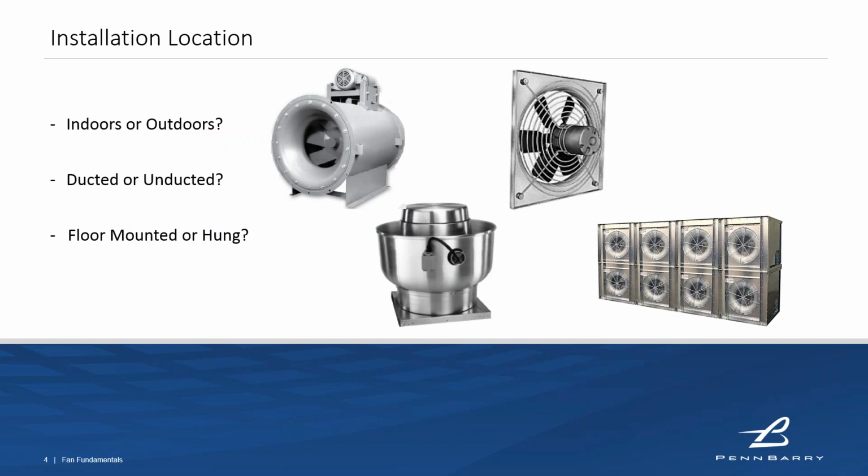So then, going into installation locations: are you going to put this fan inside? Are you going to put it outside? Is it going to be on a roof, on a curb? Is it going to be inside of an air handler? These are all things we have to think about. Whereas one is going to use this mounted on a roof curb, they're never going to consider a propeller fan for that same type of application. And if it's got to be ducted on inlet and outlet, well, now you're really into either a tubular fan or a housed centrifugal fan.